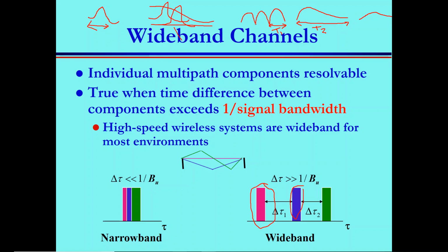If you are sending your symbol back to back very quickly, what happens to the duration of the symbol? It shrinks, and it shrinks to a level where its duration becomes less than the spread in your medium, whether optics or copper or wireless or transmission lines or whatever. In this case, definitely you are going to face inter-symbol interference and delay spread in your channel. Two reasons: the channel, the filter you use at the transmitter, and the speed of data rate.